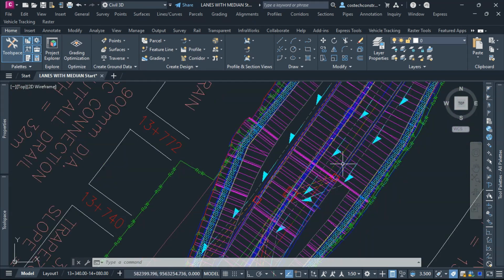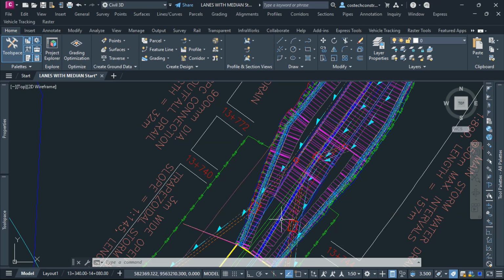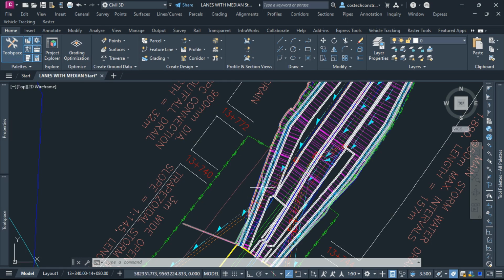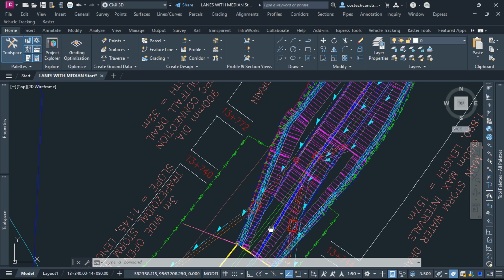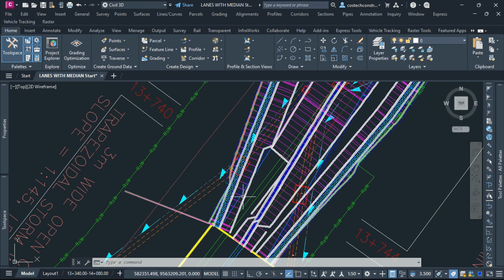We'll need to create regions at this area below so that we can satisfy the corridor conditions for this design. Like example, this first part here, we only have median tying up to the service lane. We don't have the right and left islands up to this point here.